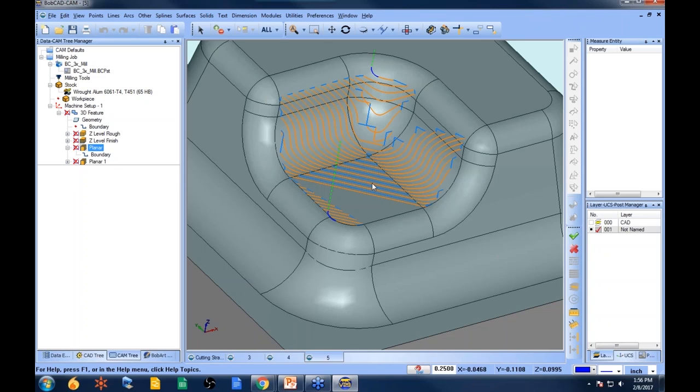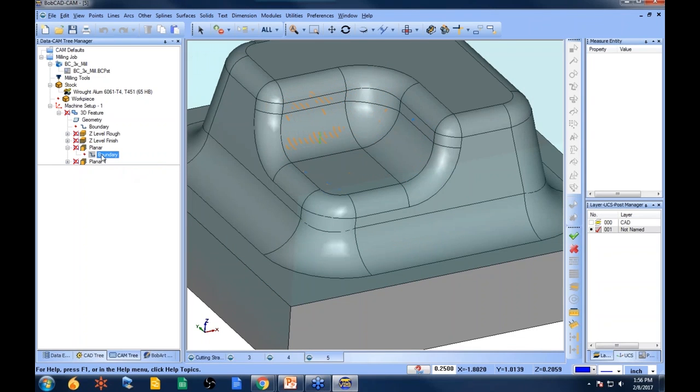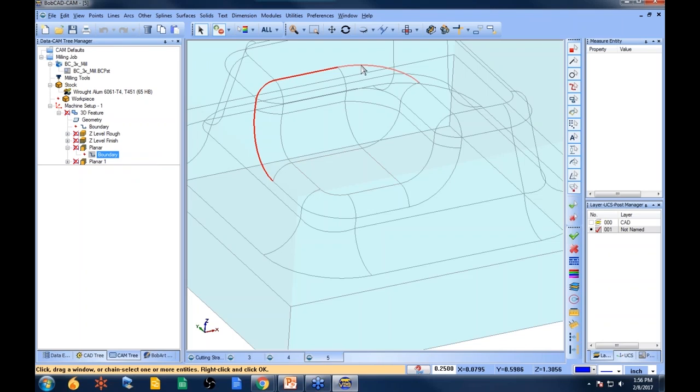It can just get that one boundary. When you start selecting multiple surfaces, you tend to run into issues as a boundary. A lot of times what I would do is select around these edges. Now another trick I'll do is I'll turn the shading off because it makes it a lot easier to select just the edges that you want to work with, okay?